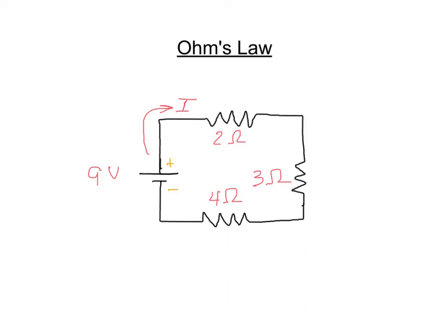I'd really like to know how much current is in the wires, because that's how electricians know how to size the wire. If there's going to be more flow through the wire, just like a pipe, you'd want a bigger pipe. Same thing with wires, you want a larger wire. Wires heat up when current goes through them, so if you have too much current going through a small wire, it could overheat and cause a fire. So when you do circuit analysis, you're trying to figure out how much current is going through each branch of the wire. And circuit breakers are also sized for that reason.